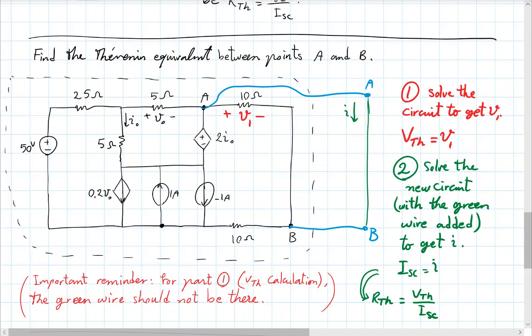So that's what is meant when we say between any 2 points, when we define the Thevenin equivalent. This is meaningful as long as we haven't connected these points to something else somewhere else. So that's one really important thing I wanted to emphasize: you have to make sure that the rest of the circuit is contained in a box, not connecting it somewhere else.